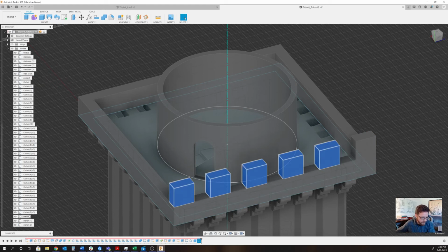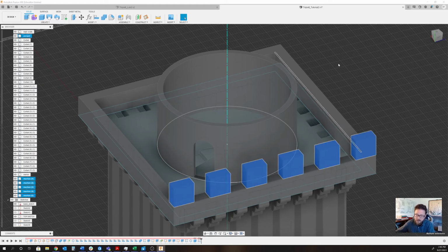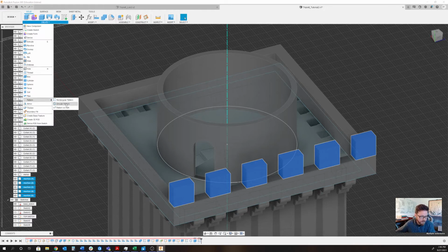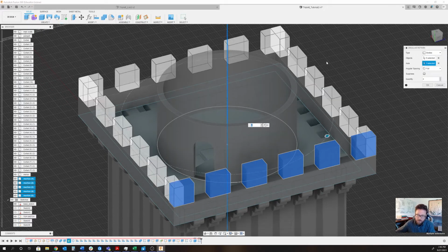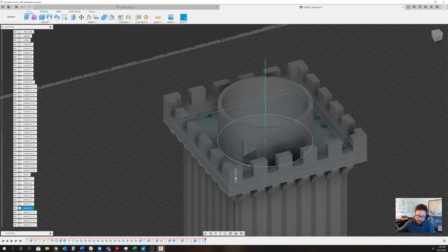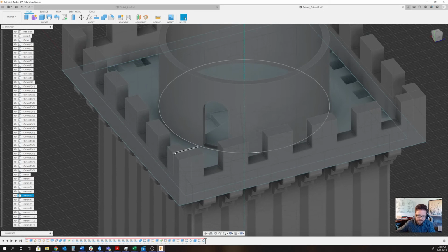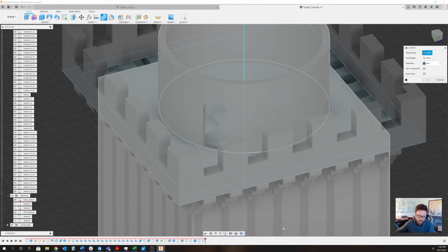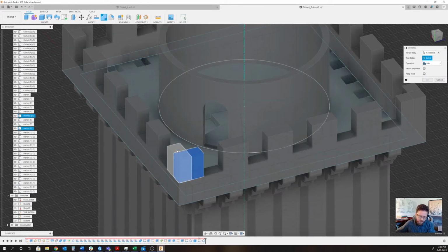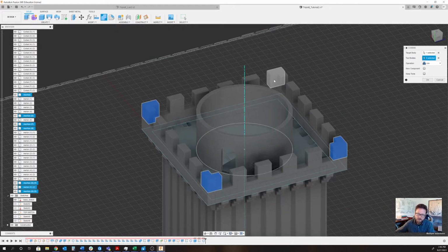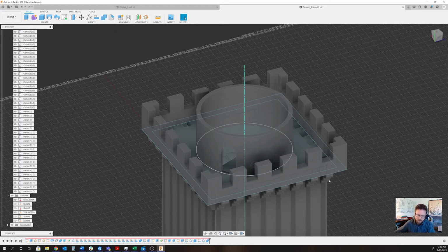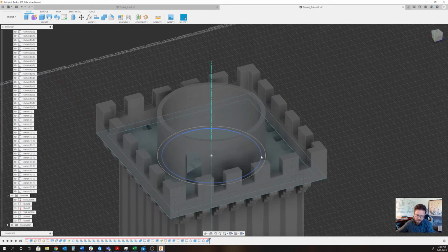So now that we've created these Merlins here, I'm going to shift select all of those, and I'll create another pattern, and this should be obvious what I'm about to do here. We have 4, and we're ready to go. Okay, something that I don't really love about this process is the way that it creates some interior faces here. It just sort of aesthetically bothers me a bit. So you can attach all of these objects to each other, or just do a handful, and make sure that this is set to join. And anything that's touching each other is going to be one object. Okay, so now all of those are corner points rather than just being 2 objects embedded with each other. That's me just being particular.